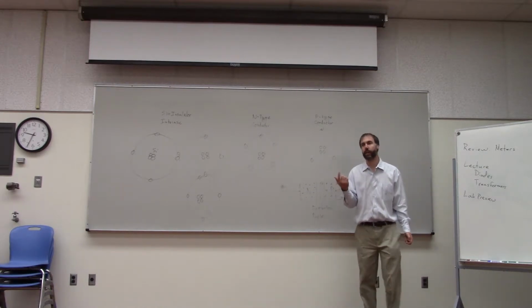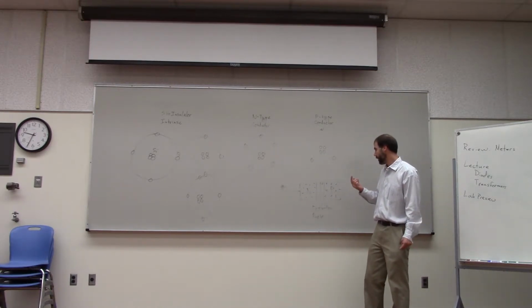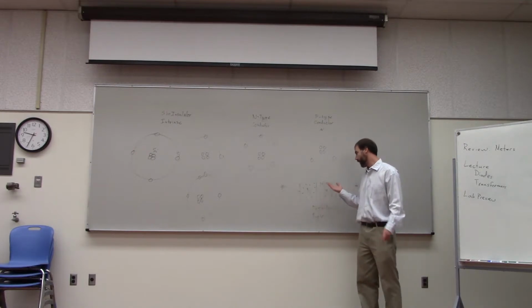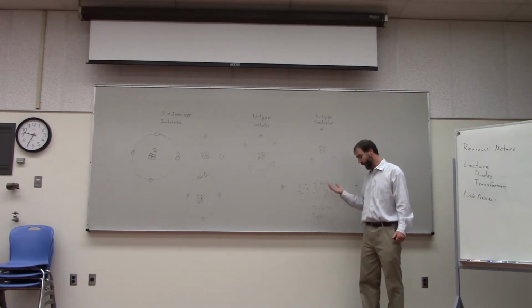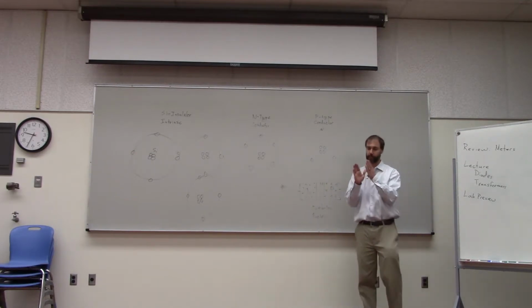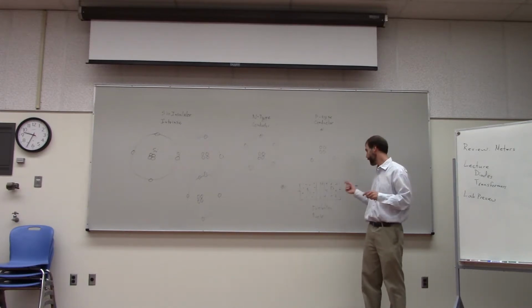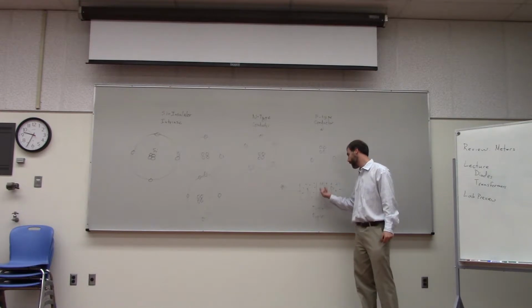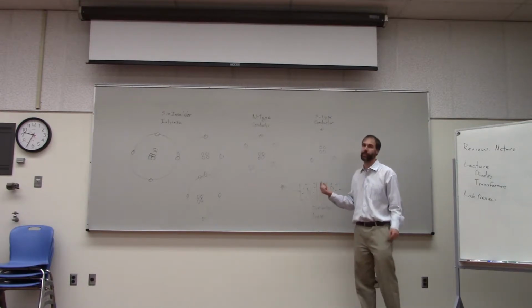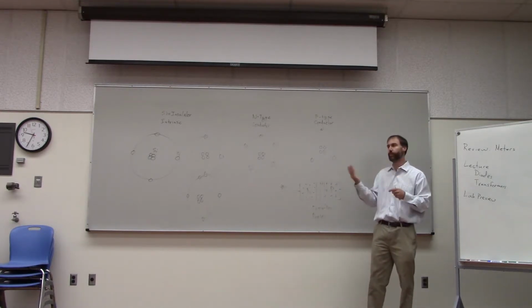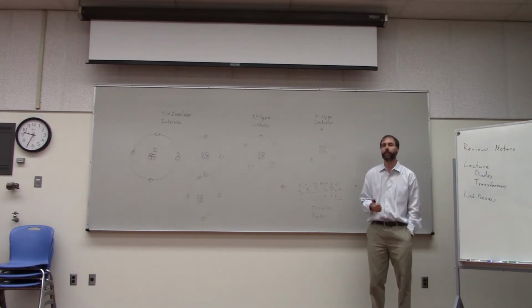What it's really doing is using a varactor diode in a radio receiving circuit, and it's putting a specific voltage on that diode so that you get a specific capacitance, and then that capacitance tunes in the station that you want. So yeah.